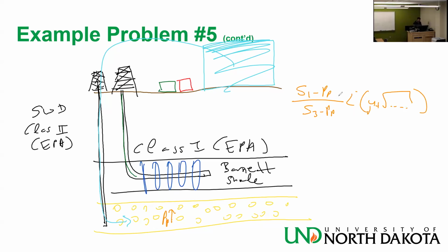But then you increase this PP, and you get to a point where this is the case. Now you are in trouble, because you can have a pre-existing fault here. If you increase the pore pressure, you are going to make the fault slip. In shear, you have an earthquake. If there are big faults, you get a lot of earthquakes.